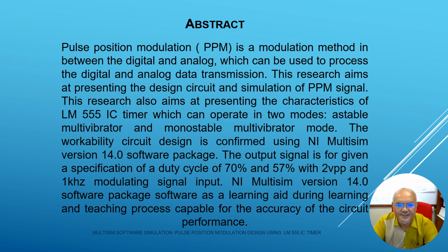Abstract. Pulse position modulation or PPM is a modulation method in between the digital and analog, which can be used to process the digital and analog data transmission. This research aims at presenting the design circuit and simulation of PPM signal. This research also aims at presenting the characteristic of LM555 IC timer, which can operate in two modes, astable multivibrator and monostable multivibrator mode.